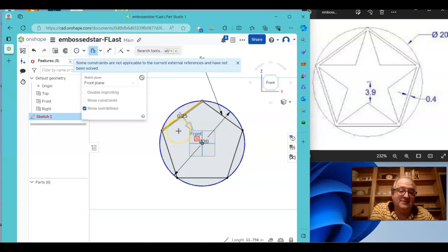Don't worry about that. Just go ahead and left click it, and then the dimension tool comes up, so go 0.4. And I have to do the same thing now with all of these. So change the arrowhead, click 0.4, enter. So we'll click on this one, click on the arrowhead to get it to go the way we want it. Kind of come over here, left click, 0.4, enter.